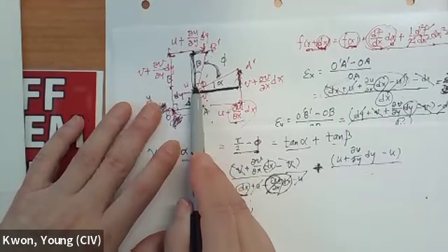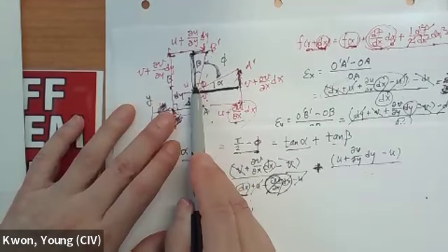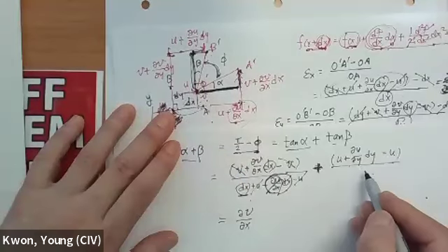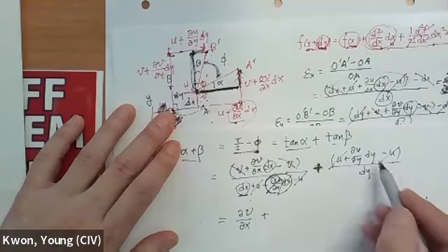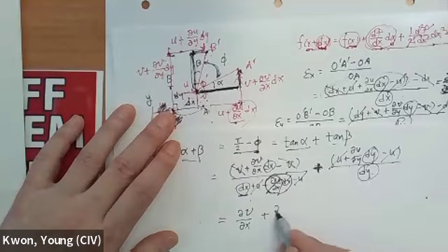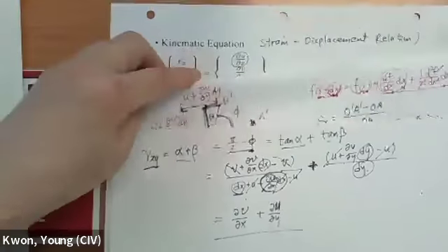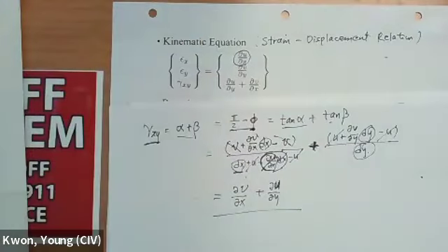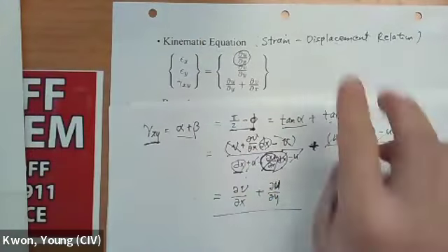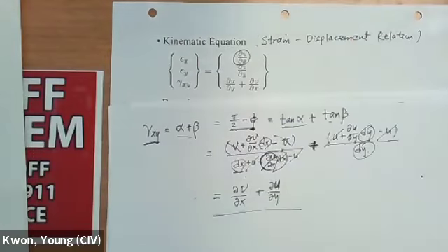And this distance, same thing as we did, we can easily say that it's almost equal to dy in the simplification. So this one cancels out, and you get du/dy. So that's what you get in here. Okay, so that's the distortion. So change in angle, shear strain.